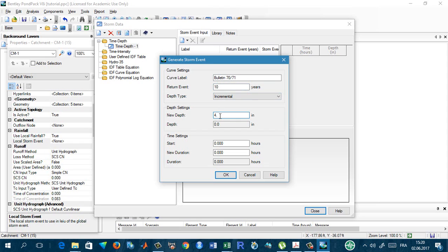I think, I mean, the idea behind this is that we are going to generate a storm event, you see, from data that is already or synthetically prepared, like a synthetic hydrograph, you see. There is like a unit hydrograph. A synthetic hydrograph is developed simply from the catchment characteristics: slope, length, area, catchment shape, something like that.